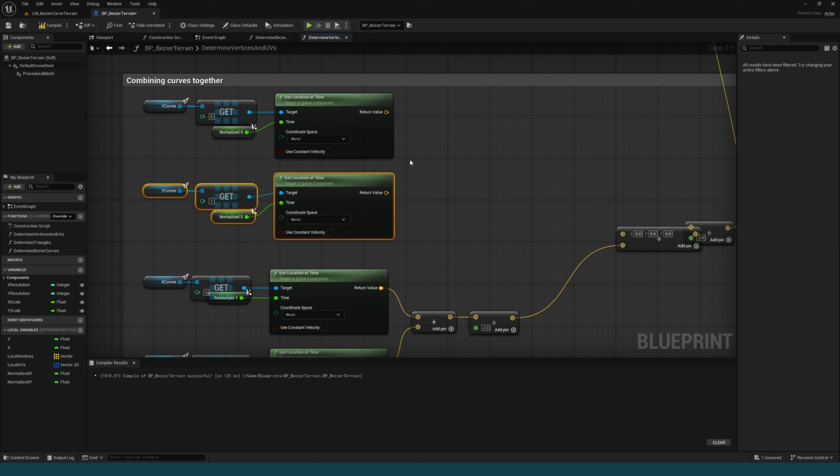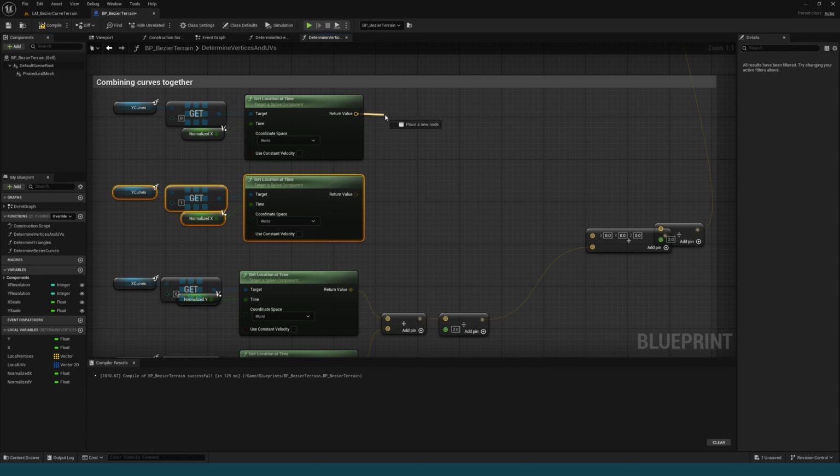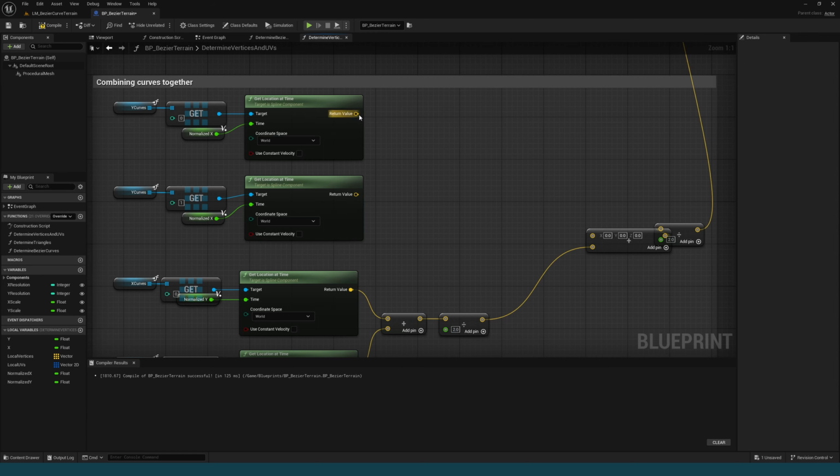And that way we don't need to scale it in any way, since we're only using that one curve and not the other. And then for intermediate values, we can add the position from those curves based on a weighting of those curves. So if we're directly in the middle, we'll use 0.5 of this curve and 0.5 of this curve. If we're at a value of y equals 0, then we'll use 100% of this curve and 0% of this curve. So to do this, let's go ahead and drag out our position here,